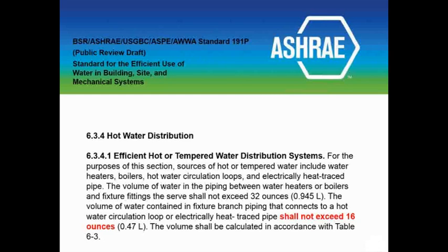You can't run 50 feet anymore, guys. You're going to have heat tracing tape, or you're going to have to recirculate right up to the fixture. That's the message I want you to understand. The world is changing. Be aware.